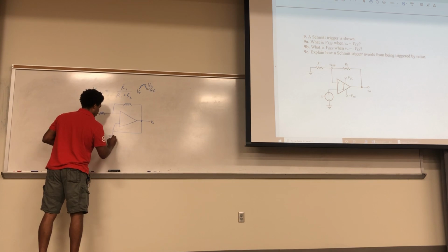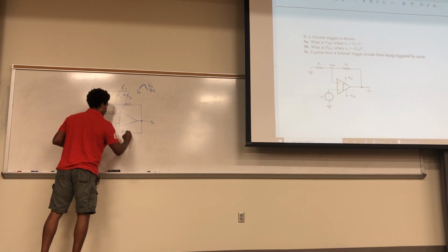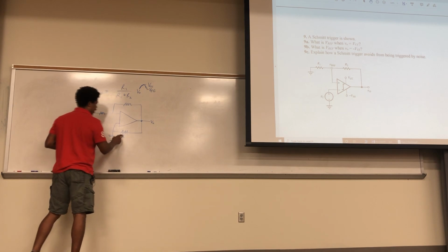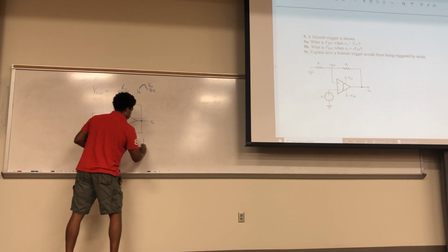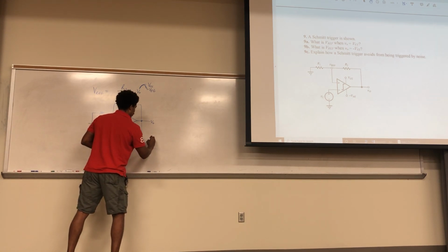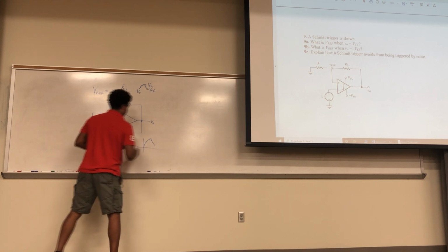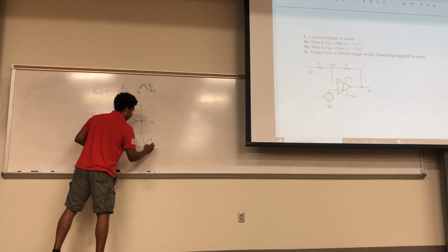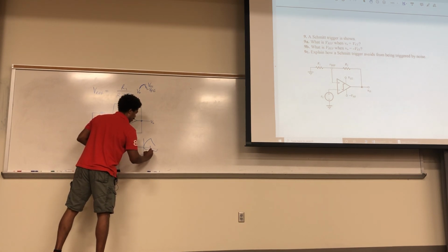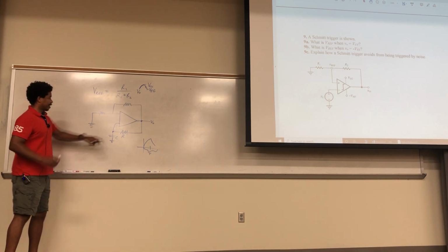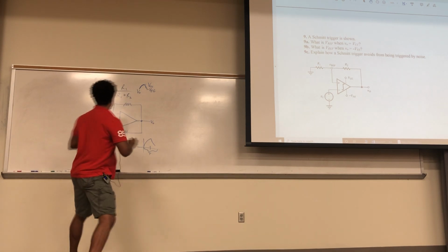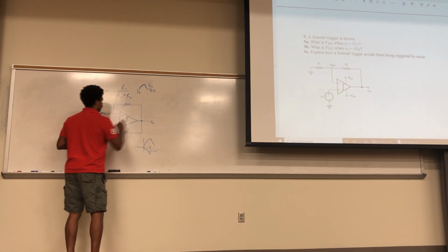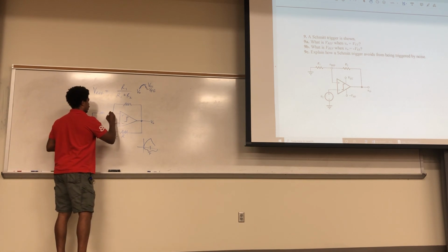Put a capacitor here and a resistor. So this RC right here has a time constant. As this capacitor charges, it takes a little while to get to where it needs to get to before it starts discharging. What this allows you to do is find out whatever your period is. So that's what this does. Okay, and this is your comparator and your Vref right here.